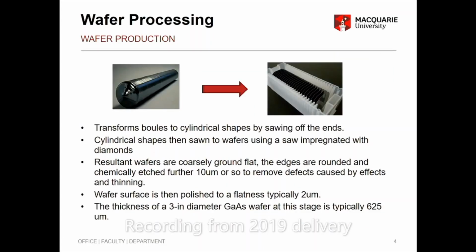Now once you make this, you have to go for the second step, wafer production, which means you need to slice it and get wafers as we see here. So there are multiple sets of wafers. They are just semiconductor discs. So you actually have to saw this first, maybe trim the edges, similar to slicing something, right? So you use diamond-tipped saws because you need precision cutting. Still, it will be coarse when you cut it. And so your GaAs, is that 100 micrometer thick or 50 micrometer?